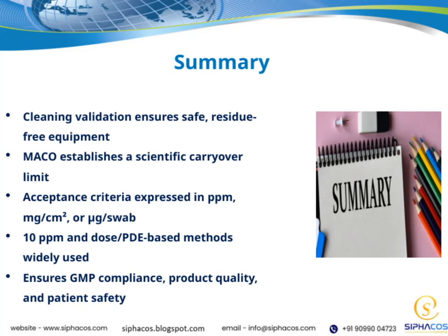Cleaning validation is a critical step to ensure that our equipment is safe and free of any residual contaminants. MACO plays a key role here by establishing a scientific carryover limit, which helps us determine acceptable levels of residues. These acceptance criteria are often expressed in terms of parts per million, milligrams per square centimeter, or micrograms per swab, depending on what's most appropriate for the situation. You'll notice that the 10 ppm standard and dose or PDE-based methods are widely used across the industry.